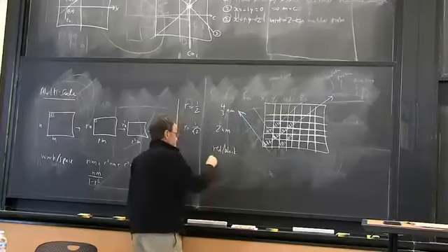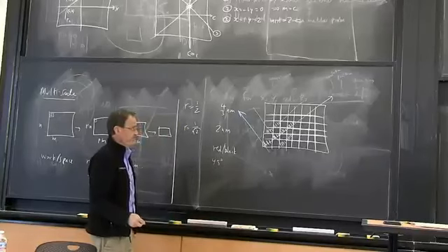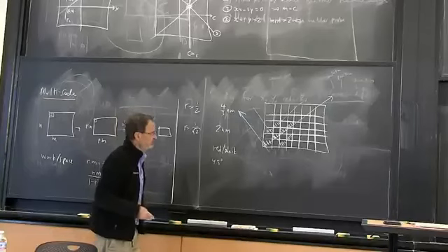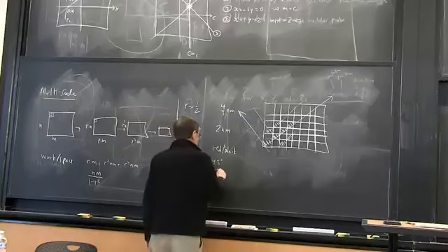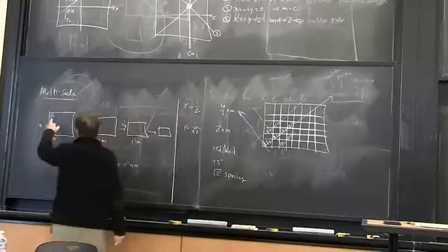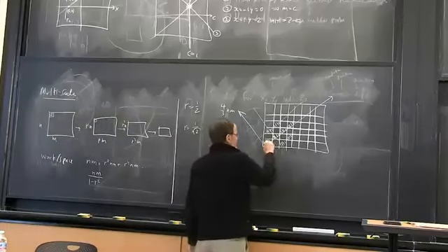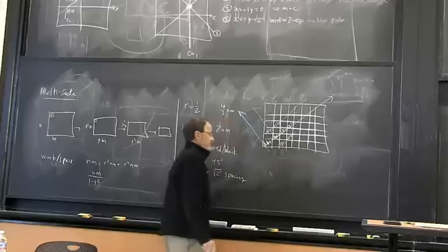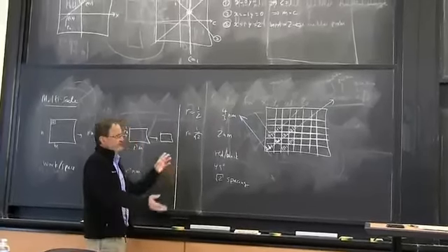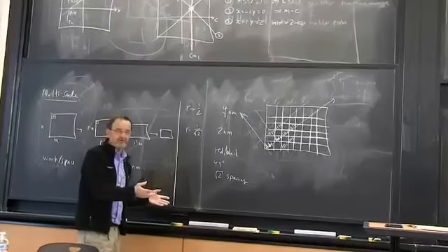So if we're willing to deal with a 45-degree rotation, this gives us a square root of 2 reduction. And the other thing it does is it increases the spacing by square root of 2. In the earlier case, the spacing increased by a factor of 2. So now the spacing between neighboring cells is multiplied by square root of 2. It's a little odd, 45 degrees. But think of it, you do it the next time, you're back in sync with the original.